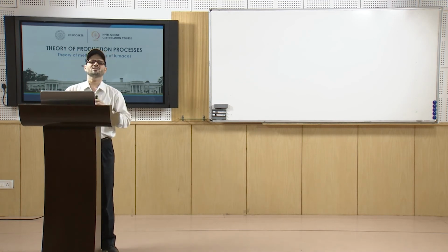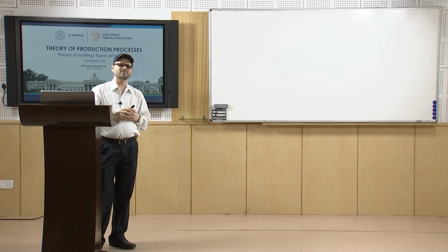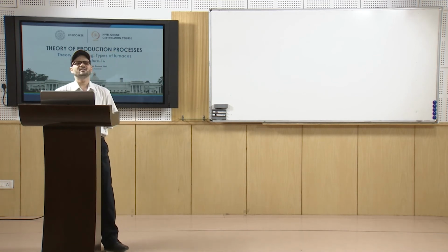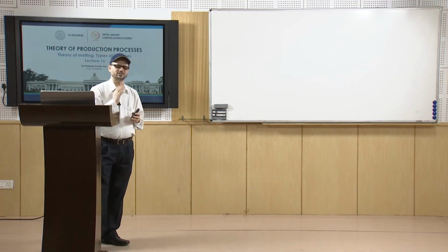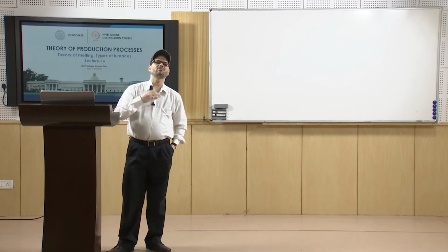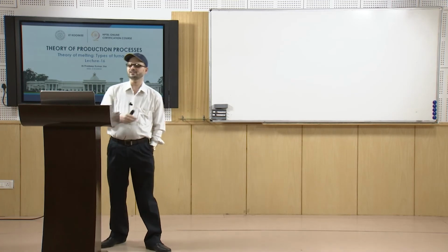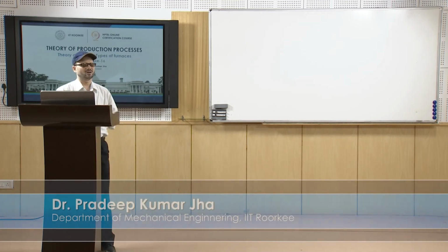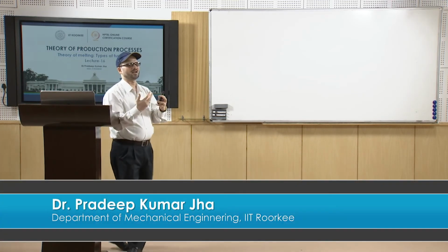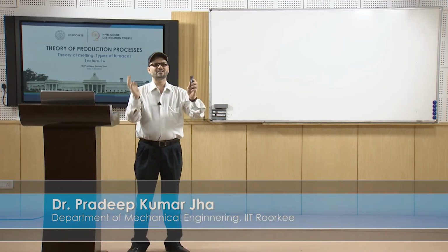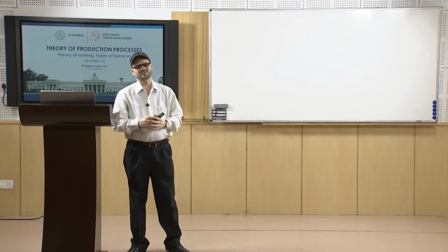Now, the charging which is normally done in these electric arc furnaces is steel scrap, 40% of heavy scrap, 40% medium scrap, and 20% light scrap. That way, that purity should be there in these cases.